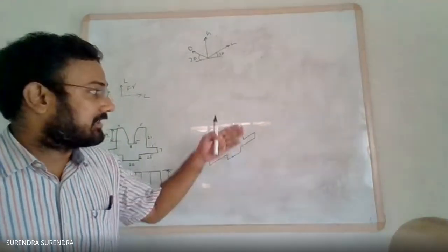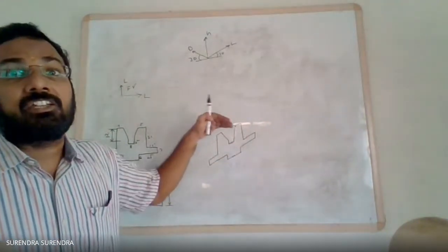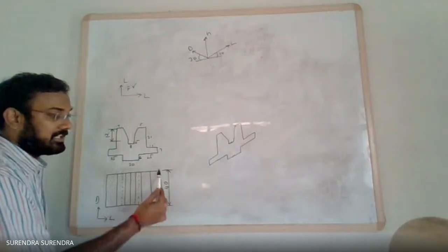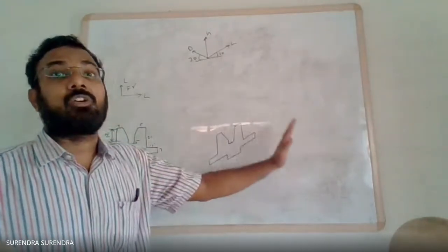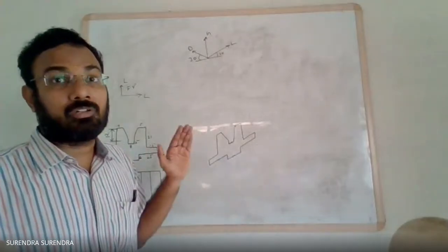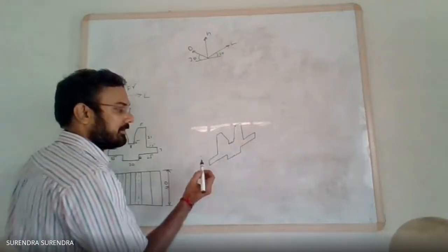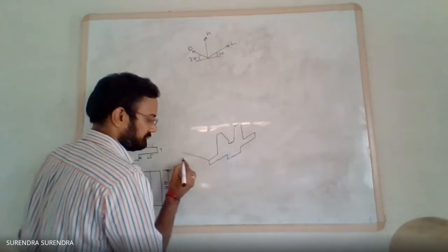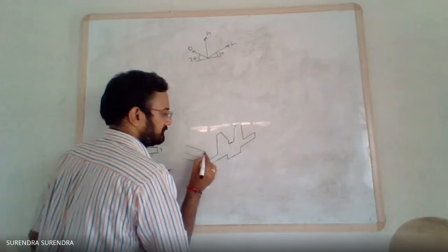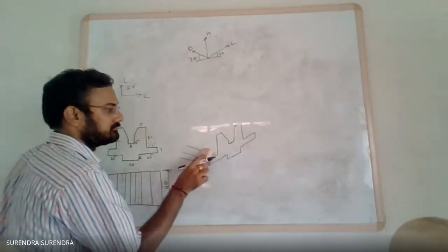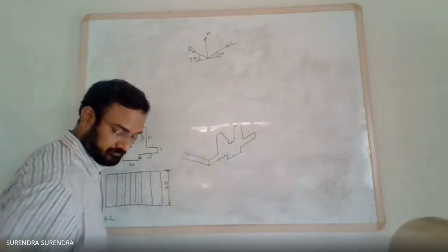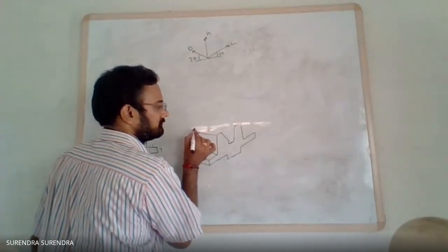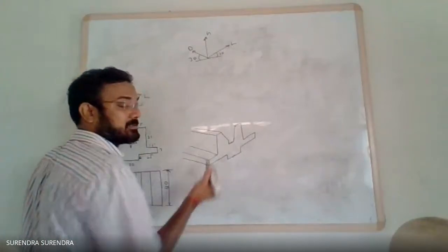After one side is drawn, to get the second side, from each and every corner draw a 30 degrees inclination line. Here the depth of the component is 40 mm, so from every corner draw a 40 mm long line inclined at 30 degrees to horizontal. Be careful, all these lines must be parallel to each other.